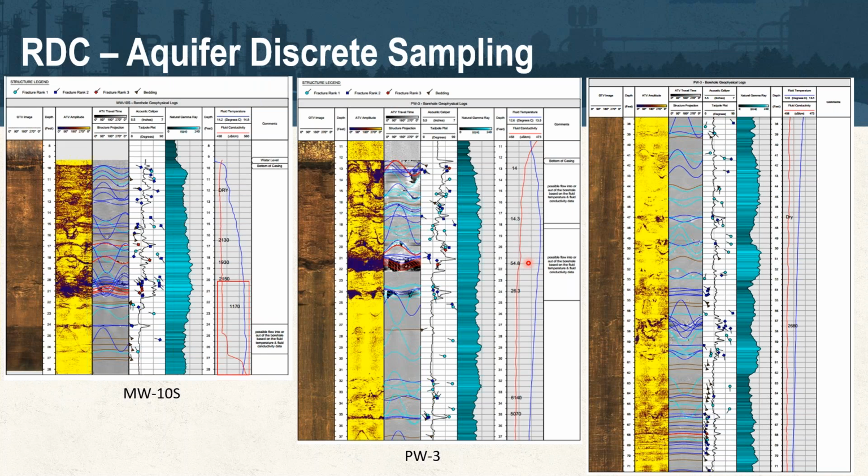But if we move further down the borehole, we can see that some of the other producing intervals present within that borehole are actually generating significantly higher concentrations of mass. And looking back at the far left-hand side at MW10S, looking at the distribution and effectiveness of that potassium permanganate, again, we're only 10 feet from this particular well, but definitely in the same flow path as where the material is injected and pulled to. We can see that even at the high K zone identified in this borehole as well, we still have elevated mass that's an order of magnitude higher than what we're seeing in the well next to it.